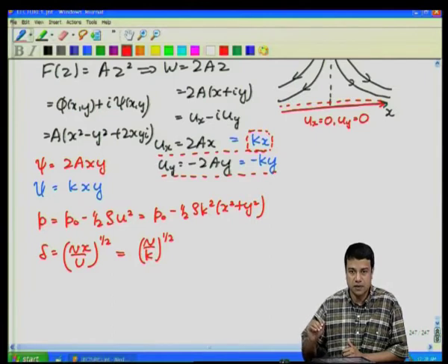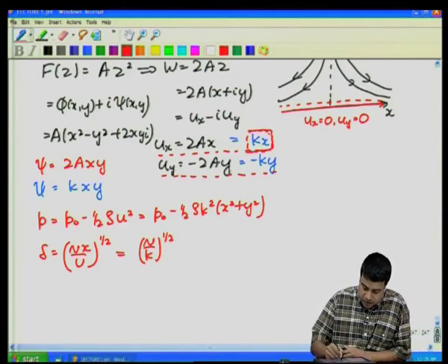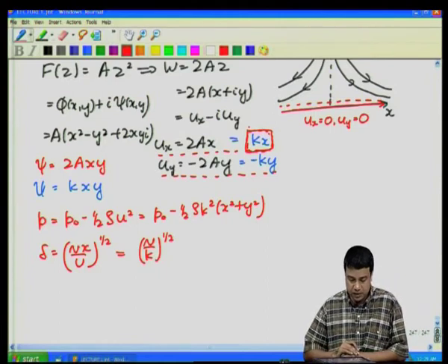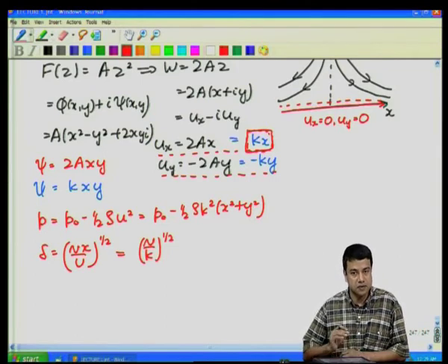There was diffusion from the surface. Therefore, I got a boundary layer which was increasing as you went downstream. In this particular case, the mean flow velocity is increasing proportional to kx, the increase in the mean flow velocity as you go downstream. So, the mean flow velocity itself is increasing, and there is diffusion from the surface. The balance is such that the boundary layer thickness itself turns out to be a constant.